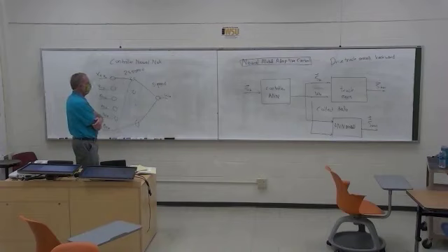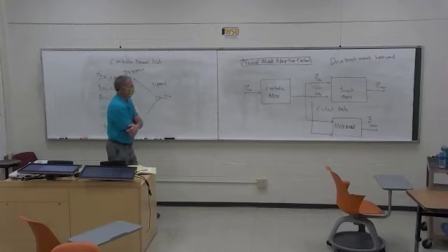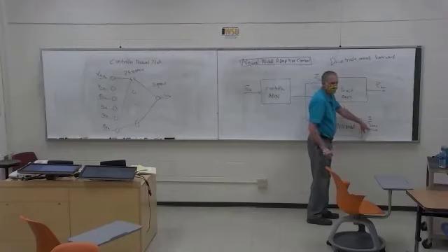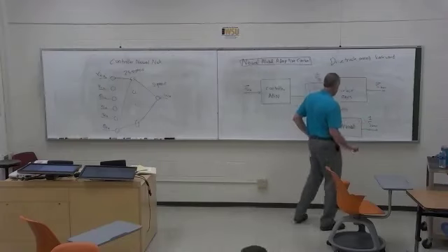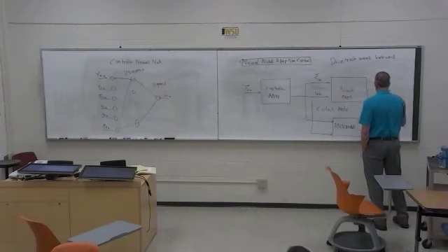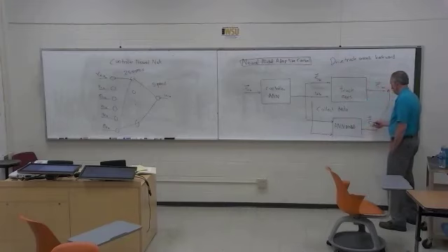We're going to train the controller by backing the truck around as well, backwards. But we've got to figure out, well, what error do we calculate to train? And how do we train the controller? Now, if we're training the model, we use the data from the model. So all we're doing is saying, well, right here's the neural net answer. Here's what we really should have gotten. So this is the model error.